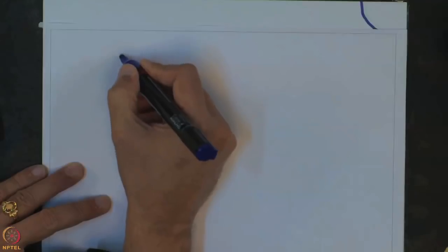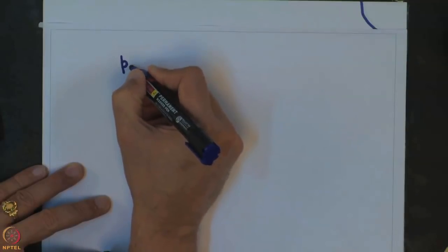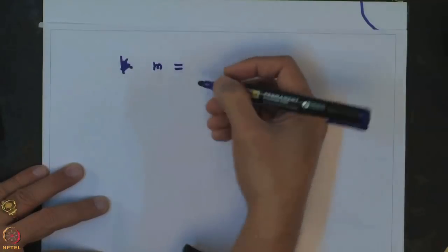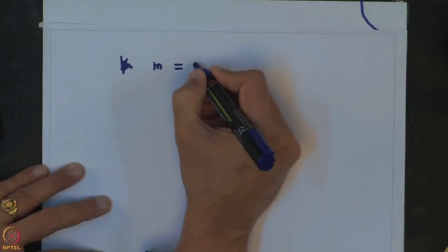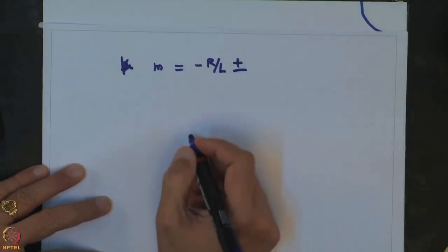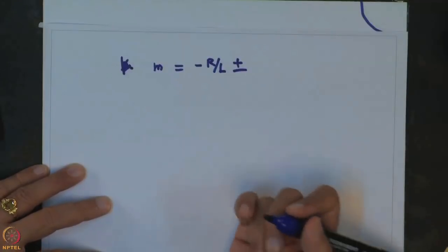So, basically it is a transient response which lives for a very short time, also called the natural response, as it depends on the circuit parameters, the various elements that are used, L, R and C. It does not depend on the applied function, the forcing function. So, if you want to determine the natural response, we know that P1, or we can just call the general expression M, denotes the roots of the quadratic expression that we will get by substituting the right hand side, the forcing function, equal to 0 in the previous equation. So, the term Vm omega by L cos omega t vanishes, it is 0. This becomes the homogeneous equation, and then we are trying to find the roots of this equation.